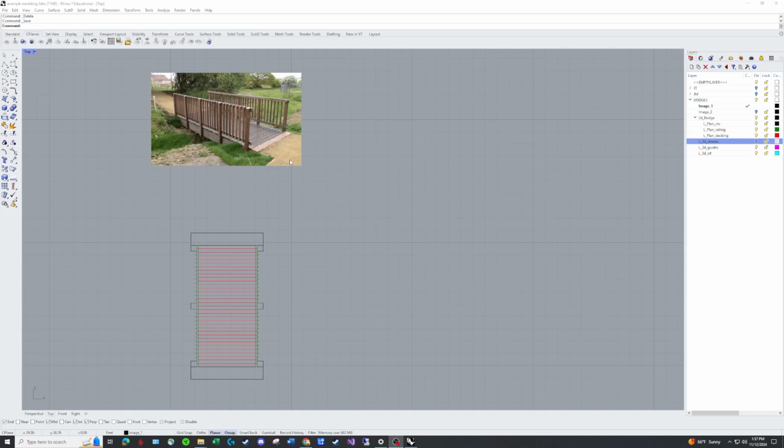So in this video, I'm going to show you how to do a really simple flat bridge that crosses a shallow water feature. In some cases, I think you could do this bridge without the railings and balustrades because the drop is more than likely less than 30 inches. You certainly could in your designs make your drop less than 30 and then you don't need any railings.